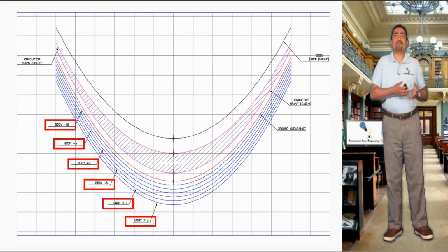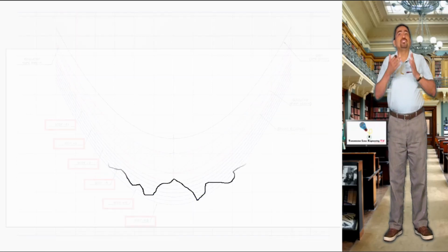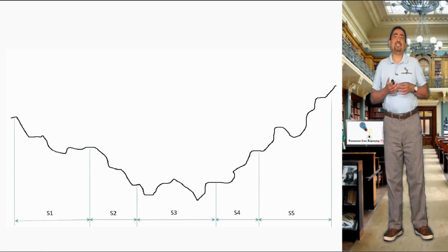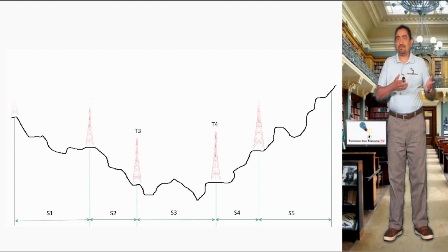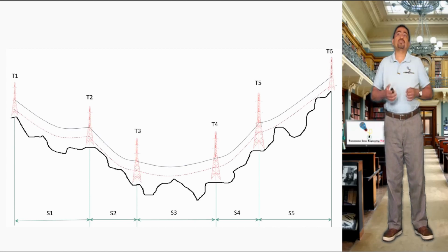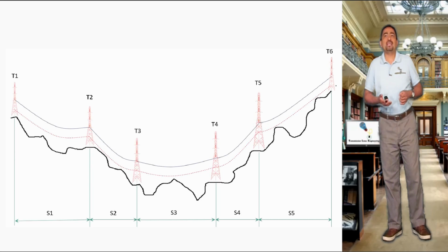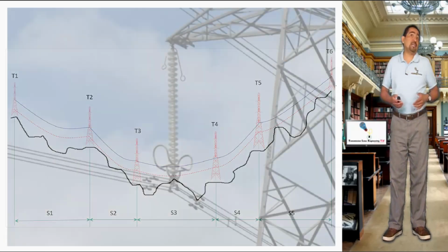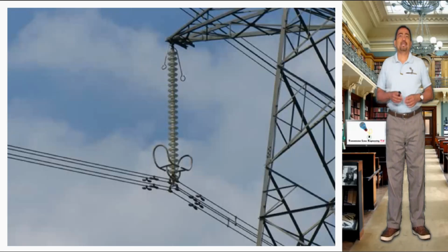In this way it was possible to adjust the extension of the catenary to the topographical needs of each project, making it possible to evaluate different location options to find the most economical option, reducing the number of structures, construction time, and maintenance as well.